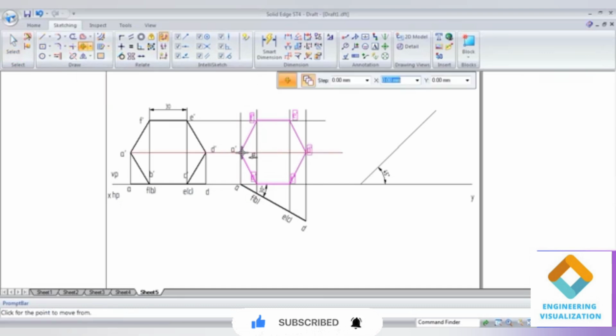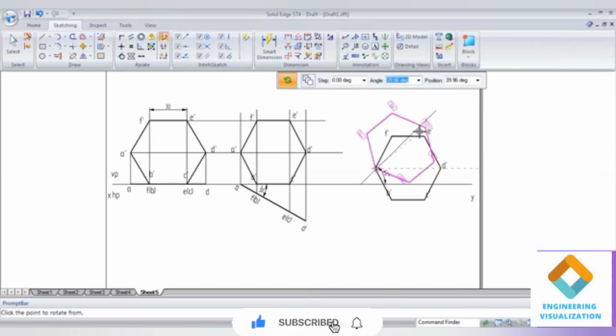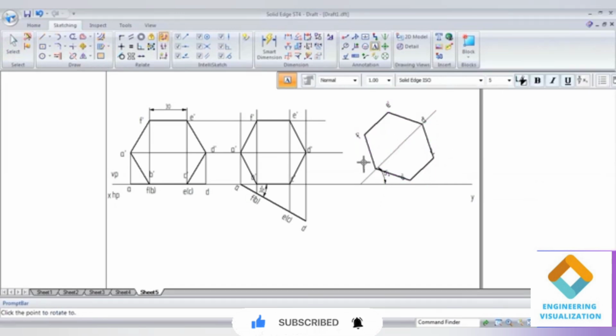Now select this second position, and then copy it on the angle line with respect to the diagonal. Because in this problem the diagonal is given, and it is an appears-to-be type of problem, that's why we need to place it with the diagonal here. So place it on the angle line. Now project it downward to complete the final position.